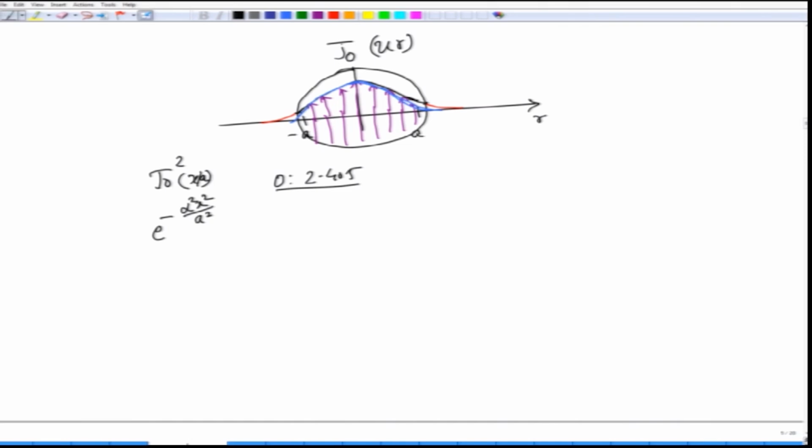Okay. And you can see here that this Gaussian approximation actually goes slightly beyond your core, right. The mode is not going to 0 there, it is going slightly beyond the core as well. So, this particular diameter, within which 90% or 99% of the energy is concentrated, is called the mode field diameter. In fact, it is this mode field diameter which is very important when you are coupling light from a light source into the fiber. Okay. So, this is abbreviated as MFD.